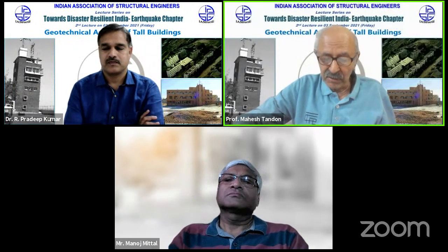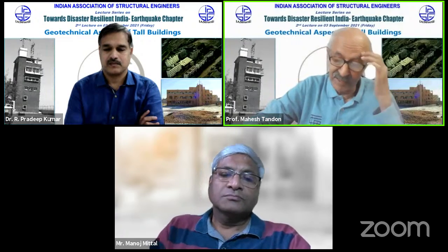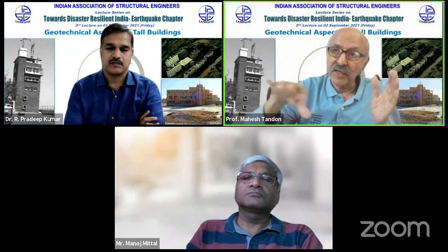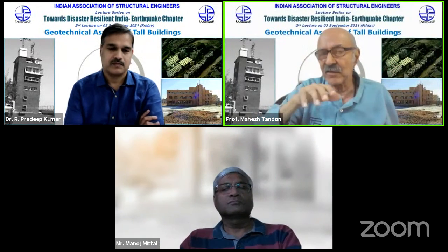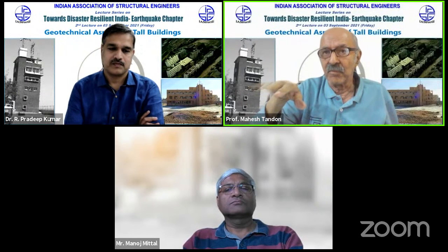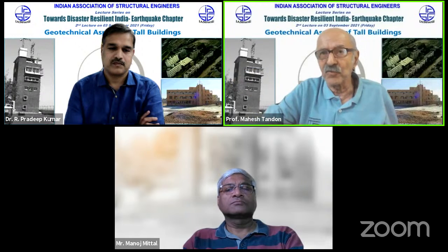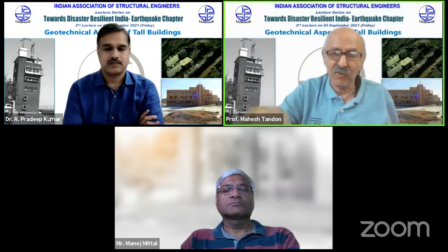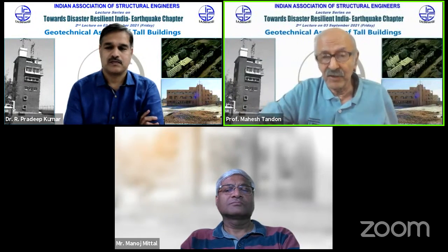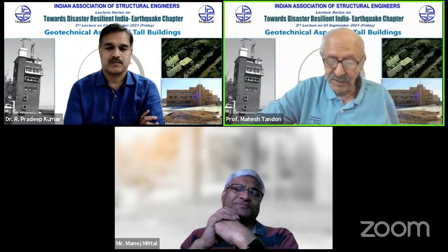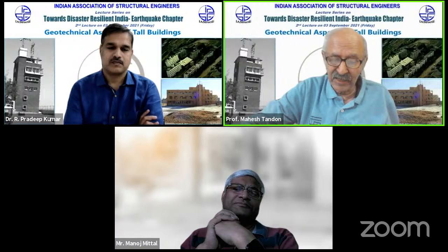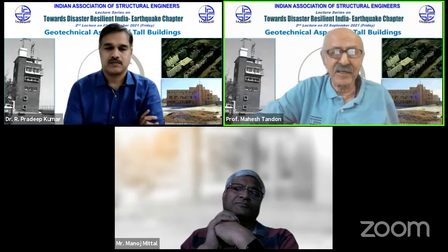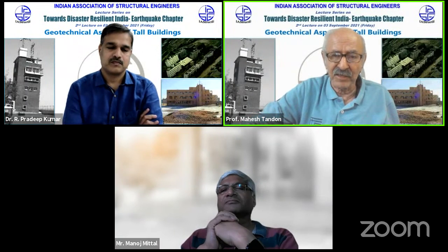The other thing is that you have a rocking motion. That means the building doesn't remain in the same configuration. It is not just moved to another spot, but you can have a rocking motion also. And of course, the building itself may deflect, even if you consider it fixed at the bottom. So there are a number of things you have to take account of when considering tall buildings subjected to earthquakes.